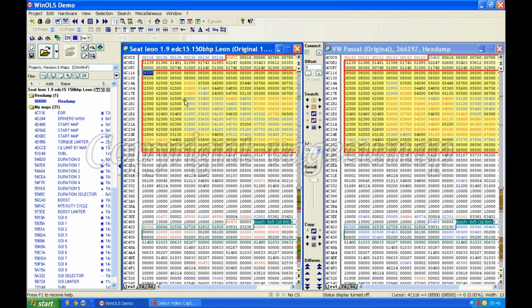Now, without spending hours and hours measuring all of these values and playing around on a rolling road, it would be quite difficult to pin that down exactly, but I do suspect that that is what is going on here. And of course, the easy way to find out with a greater degree of precision would be to get hold of two injectors, one from each engine, and do some measurements of flow rates and see just how similar or how different they actually are to each other.